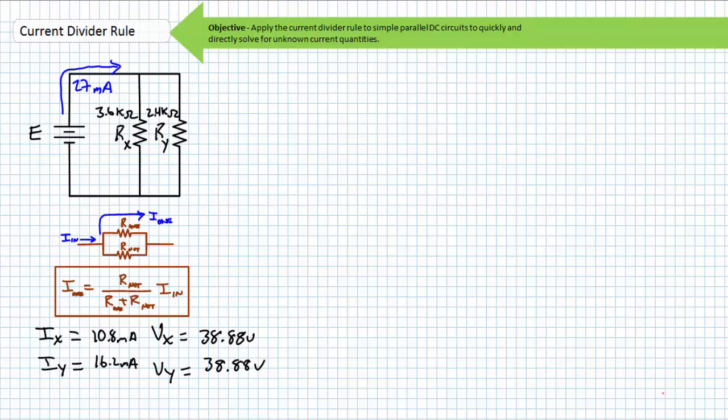In theory, current should be as easy to manipulate in circuit analysis calculations as voltage. However, in practice, the deployment of an ammeter to measure current in a real circuit is not nearly as easy as a voltmeter. The primary difficulty stems from the ammeter's requirement that it be placed in series with the element it is to measure current through. This necessitates the circuit be powered off, the circuit broken at its chosen point of insertion, the ammeter placed in series with the circuit it is intended to measure current through, and then the circuit powered back on. This is a serious drag when contrasted to the ease in which voltage measurements can be made.